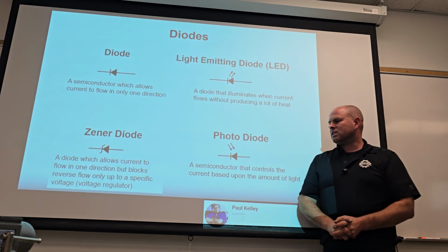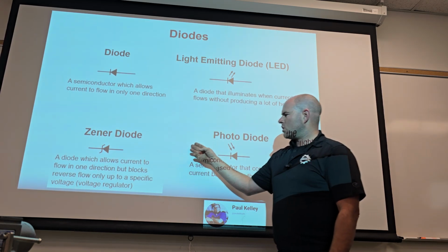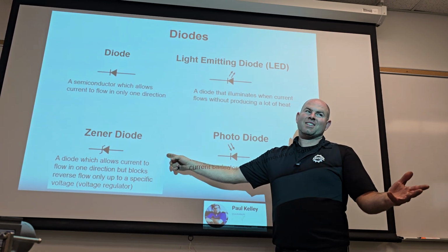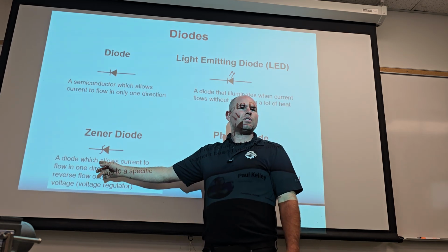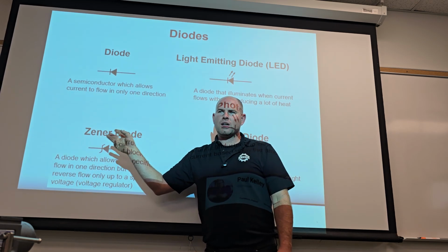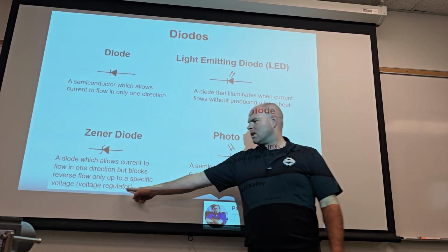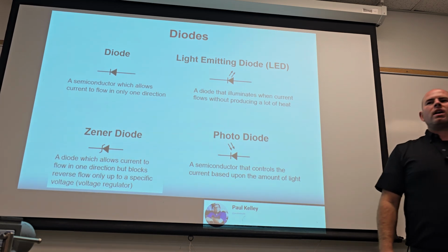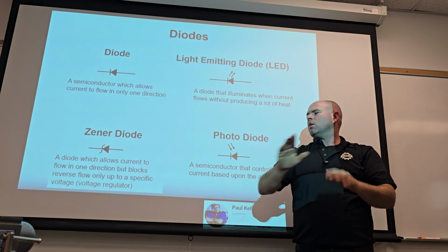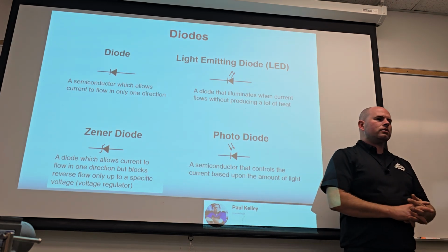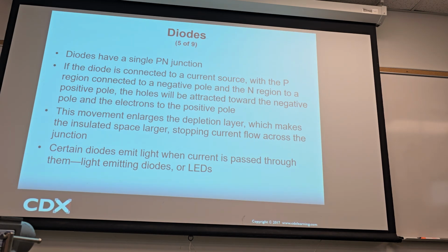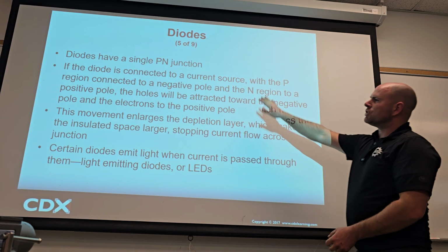Cool. So we could test these kind of similarly. Current should flow this way. Cool. Should current flow this way? Depends. What's the threshold? If it's at 12 volts and we're at 13, then it actually should. But at 11.9, then it shouldn't, right? So a lot of times we'll use this. That's what it says, voltage regulator. If we want to regulate the voltage, we want the voltage above a certain amount. We don't want the voltage going too low. We'll use a setup of Zener diodes. Pretty common. Like it? Okay, and then we talk quite a bit about the PN junction.